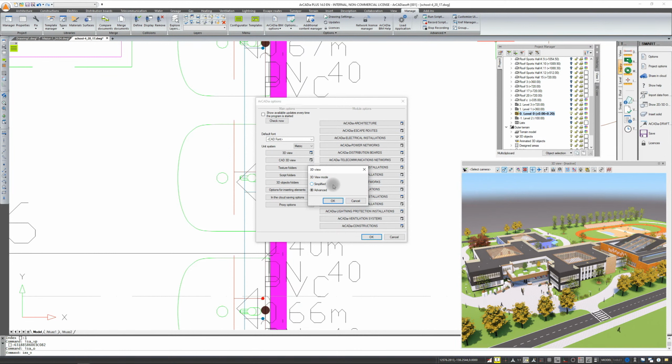You'll have no shadows, but you will have a 3D representation of your model, in which all the elements you have entered will be seen, with textures, with transparency in windows, but the program will run faster thanks to this. If you have a good card, then of course I suggest that you use this advanced view, especially when it comes to architecture. When it comes to installations, this simplified view is good because it does not show shadows, and with pipes and such elements as cable wires, these shadows may obscure the image of your project.